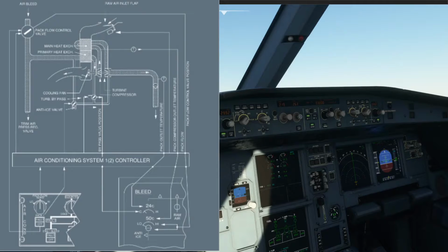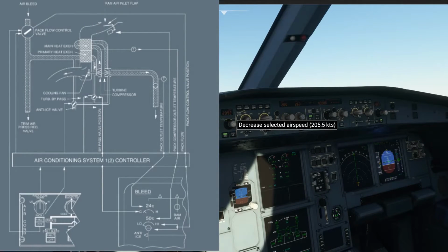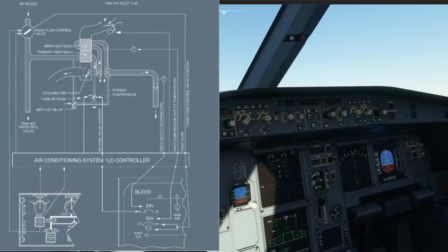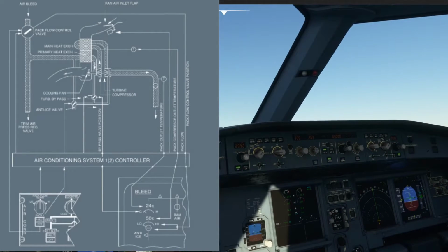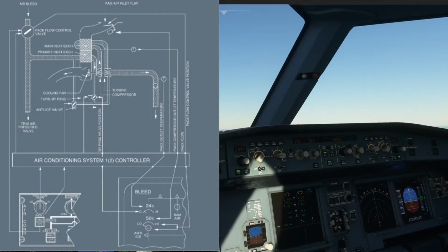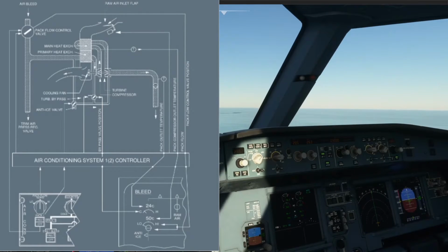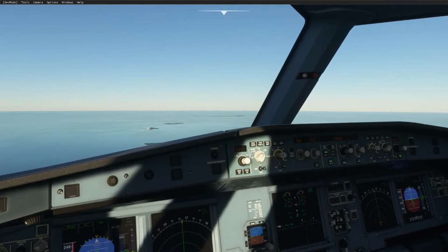You can have other fails. So what happens if, say, the compressor or turbine seizes in the pack? Well, funnily enough, that doesn't stop it. Your pack's still going to work using just the heat exchangers, and the valves will open with the relevant conditions to supply the air to the heat exchangers. However, it's going to be low flow. You're not going to get as much effort out of it, and they're going to be working harder to provide the relevant temperature, so you're going to have problems, but it will still work.